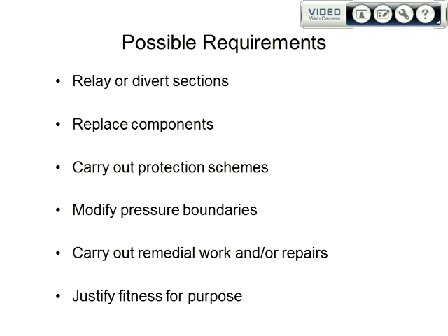Will you have to carry out any remedial work or repairs? You need to think about it. If the pipeline's been in operation, it will have been subject to deterioration, etc. So you need to think, well, if it's been managed such that its integrity is okay for a TD1 75 bar pipeline, does that mean it's okay for a CO2 pipeline?